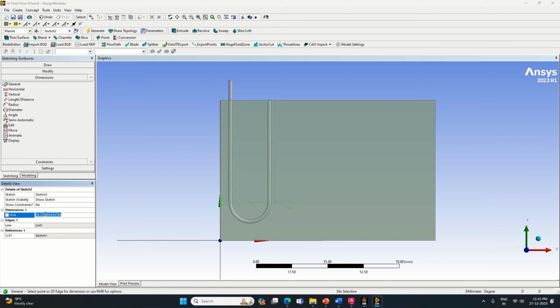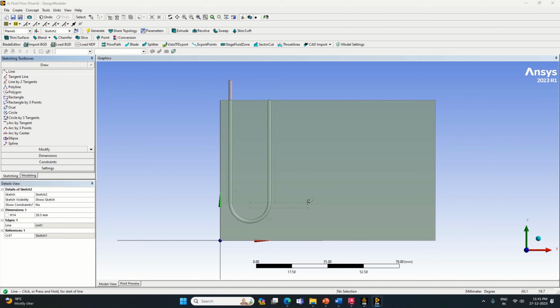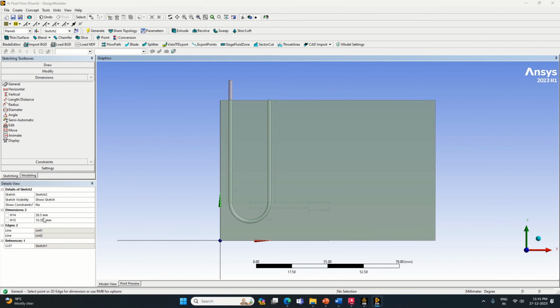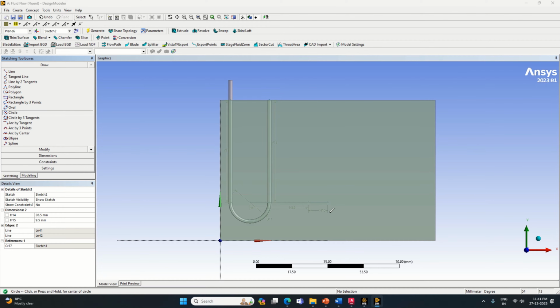Sorry, 9.5 plus 28.5, this is here. So this will be the point where we will start again. From this, take it horizontally, take a dimension equal to again 9.5 here, and draw a circle. Then draw a line which proceeds further till the vertical point.